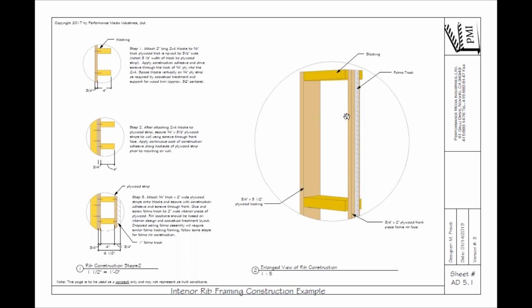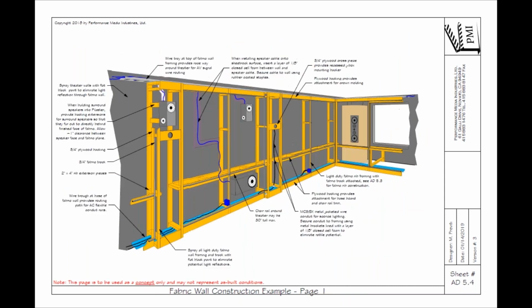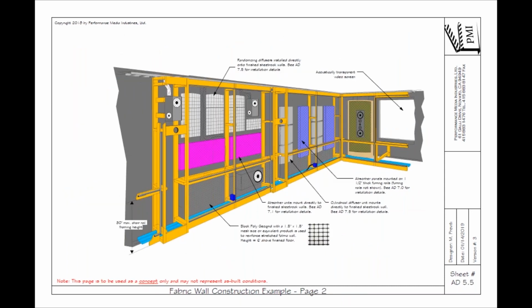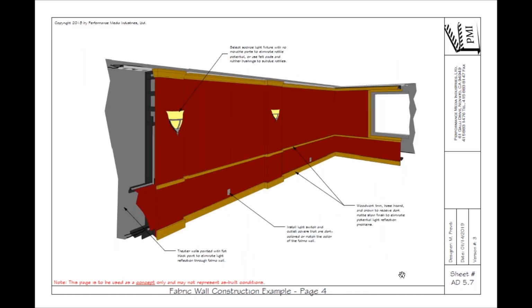So this is how we designed that skeletal material, that basic framing to hold out the stretch fabric track. The track is typically 1 inch deep, so you just need to size these kickers as blocking kickers so that it all works out. It's just one way to do it; there are other ways too. Then you build it out by first building the framing, putting the materials in there, stretching the fabric over it, and there you go.